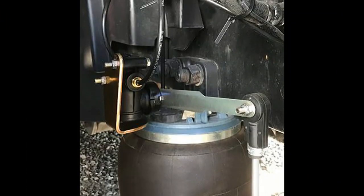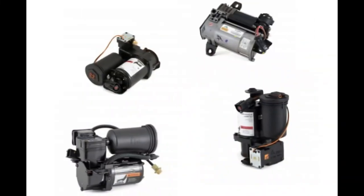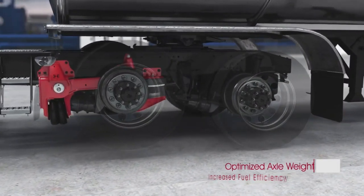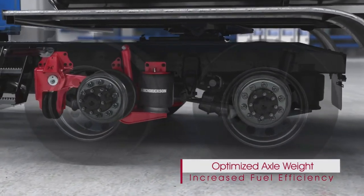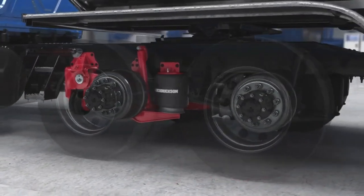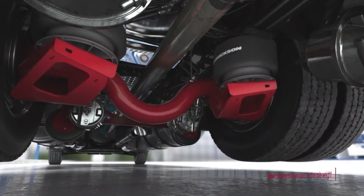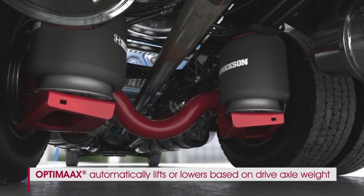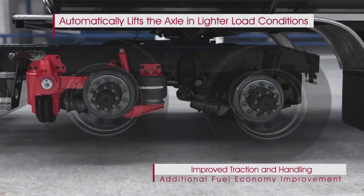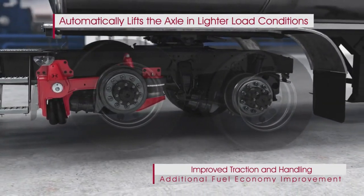Second is the air accumulator. Certain advanced compressors require a storage medium to hold the high-pressure air they generate. These storage mediums are referred to as air accumulators. Air accumulators serve the crucial role of ensuring a smooth and gradual transition between different pressure levels within the system. Additionally, a safety relief valve is connected to the accumulator to release any surplus air, maintaining safe operating conditions.